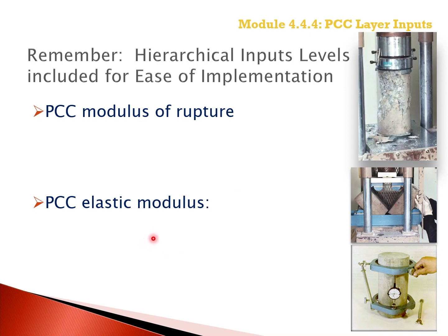Remember the hierarchical input levels for the PCC modulus of rupture and elastic modulus that were discussed earlier in the module and shown in the software screenshots themselves. The PCC modulus of rupture is the value used in the PMED software to determine the allowable number of load repetitions for estimating fatigue damage and other distresses.